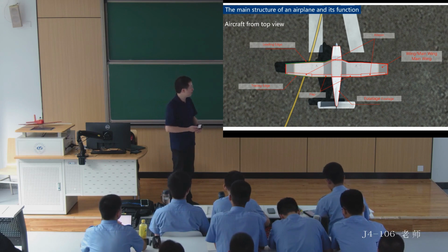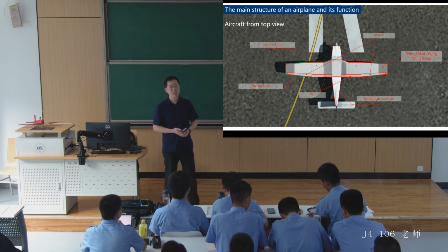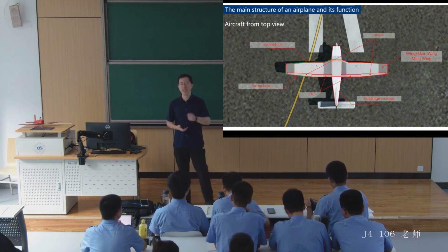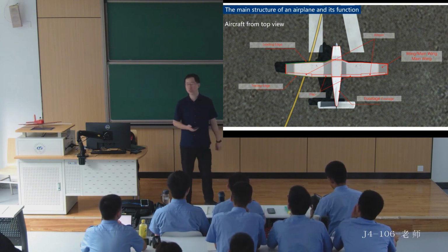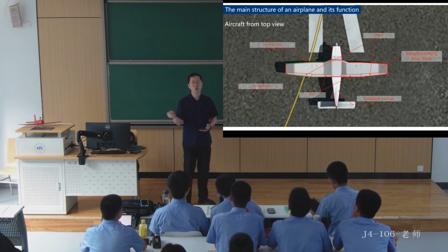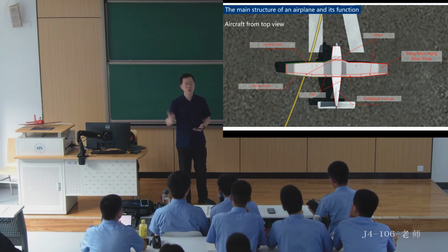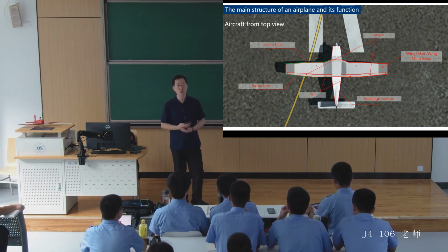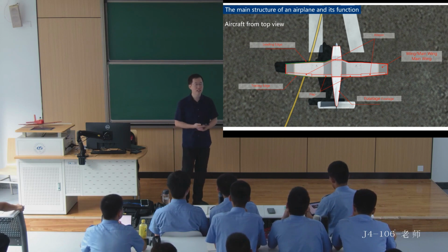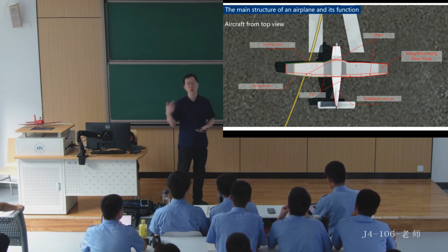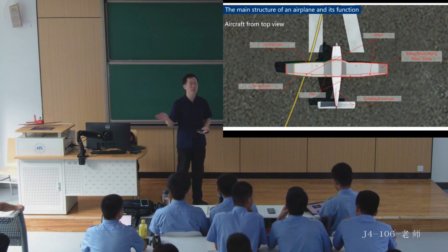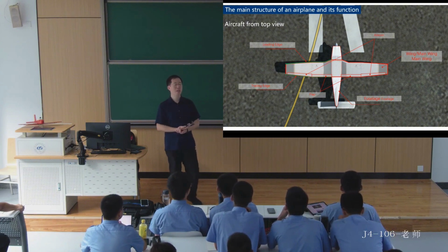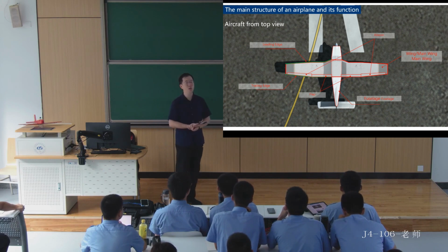it's a bit unreasonable. And also, when each of us is doing the pre-flight check, what is one of the things we need to do? It should be to move the controls, right? Moving the controls is to check whether your control surfaces are correct. How deadly it is. There have been many incidents in aviation history where control surfaces were connected incorrectly, leading to crashes and fatalities. For example, let's talk about our domestic aircraft.